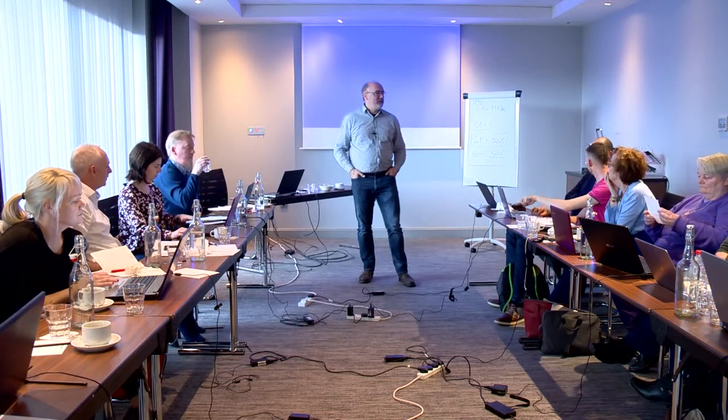As our first approach, we tried to install only wind, and we found that for our case with the 20 gigawatt hours electricity consumption, it would require between 6 and 9 megawatt of wind to balance the import-export balance over the year. Of course, we always see a lot of export and a lot of import, but still the balance would be close to 0.